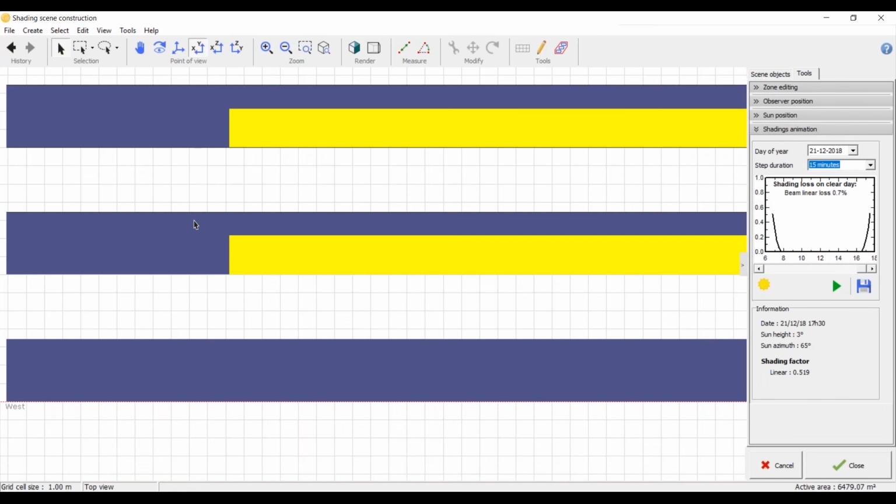This is a good one. This is something that we need to understand. Let's say, for example, you have a 10 kilowatt system and half of the system is shaded. You cannot just say only half of my system is shaded, right? If it's only one string and you say 9 out of 18 modules are shaded, then obviously the remaining 9 would not be producing half the energy that the system should be producing. Those could also be shaded because they are in one string, and it doesn't work like that, right?